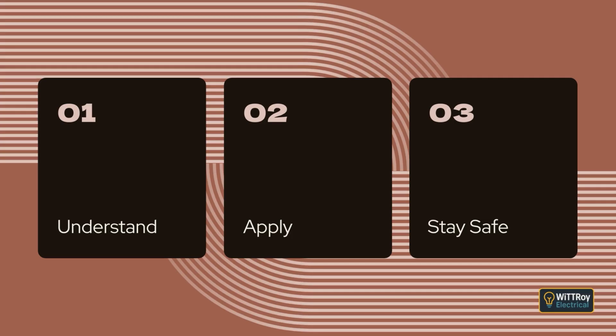Clause 3.3.2.10 Presence of fauna. Where animals or insects could damage wiring, the wiring must be selected or protected so it remains safe. Some locations require tougher wiring systems or barriers to stop animals chewing, nesting, or interfering with cables.